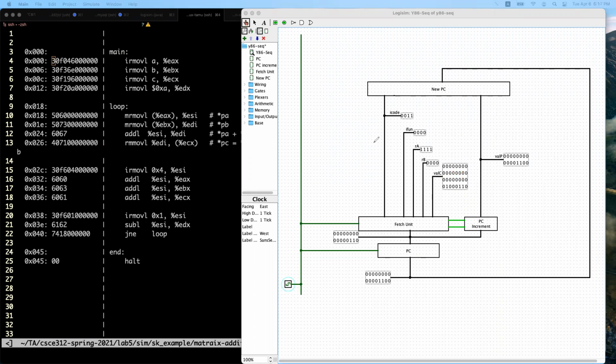So after reading the first instruction, we checked the next PC value and then produced data and control signals from the fetch unit. And then actually this next PC value is updated by the PC increment along with these 3 inputs.